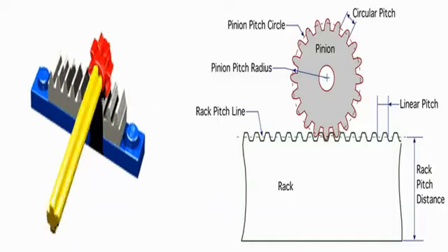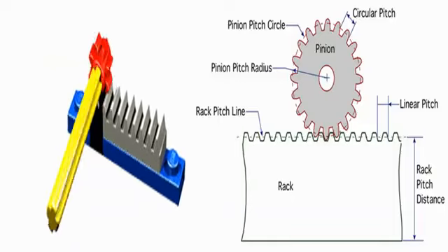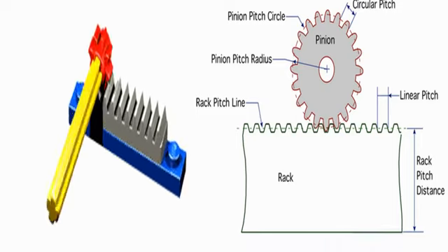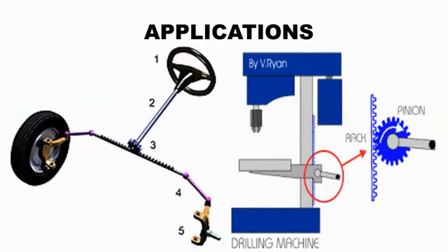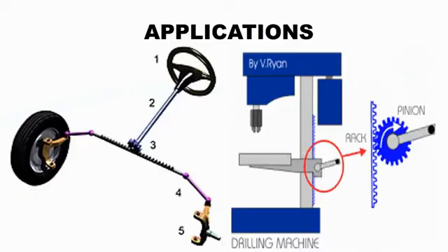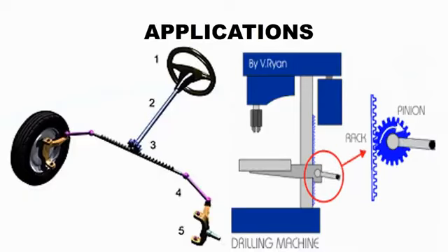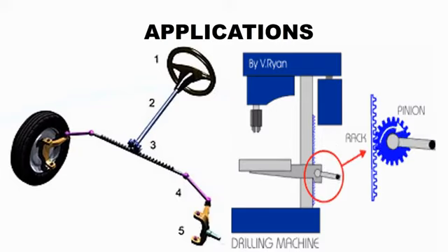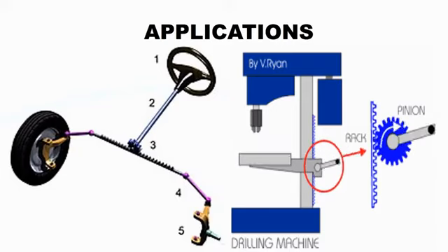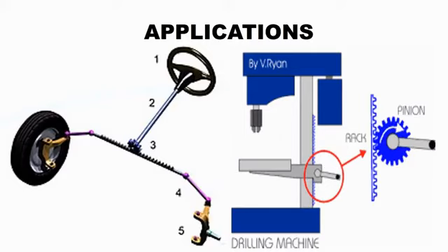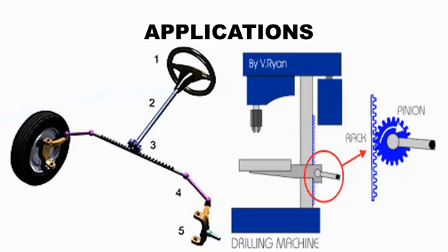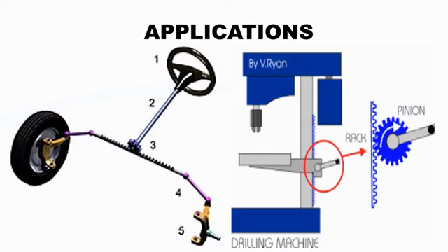For example, in a rack railway, the rotation of a pinion mounted on a locomotive or a railroad car engages a rack placed between the rails and helps to move the train up a steep gradient. A rack and pinion is commonly found in the steering mechanism of cars or other wheeled, steered vehicles. Rack and pinion provides less mechanical advantage than other mechanisms such as recirculating ball, but less backlash and greater feedback, or steering feel. The mechanism may be power-assisted, usually by hydraulic or electrical means.